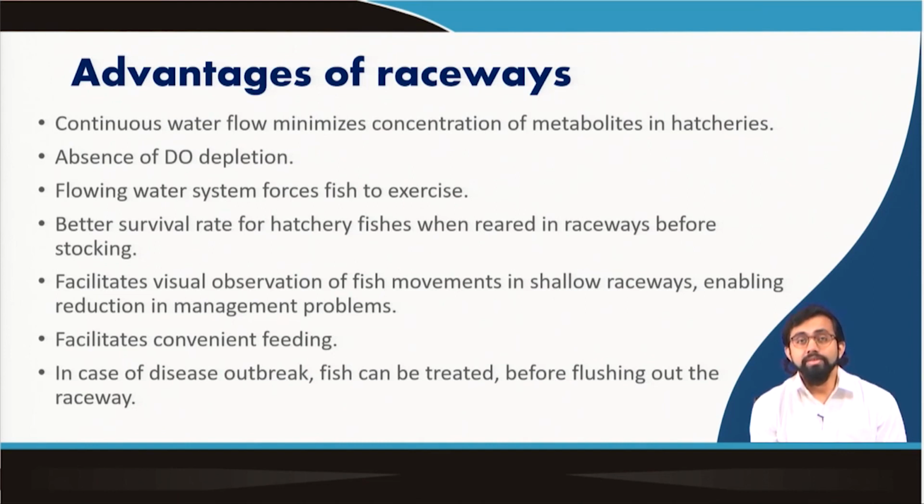It can prevent DO depletion, through the changes of fresh water, or the presence of oxygenated water. Because of the oxygenation from the incoming inflow water coming into this kind of tank or raceway system, the raceway will have a very high DO concentration in the incoming water, and it will help get rid of the DO depletion issue related to other flow through systems.